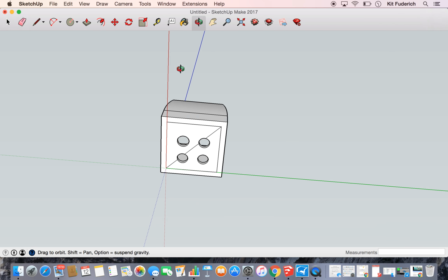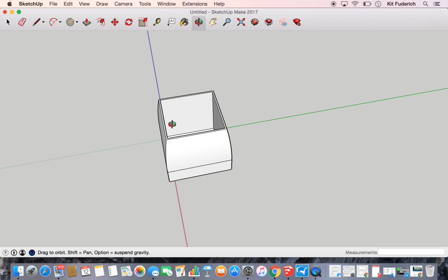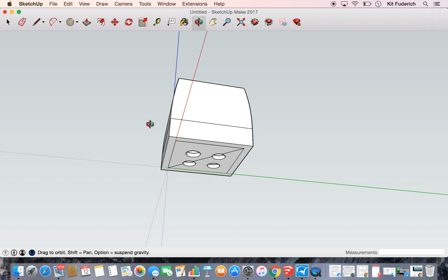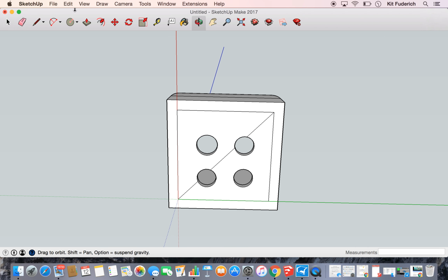So at this point it's time to create the tray for this pot, but it's always good as I complete an object to do a solid inspector, see if it's solid, and it looks like everything's good. If not, redo some steps. I'm going to clean up the bottom of my model, taking the eraser tool, and I move over each line to make the bottommost face clean.